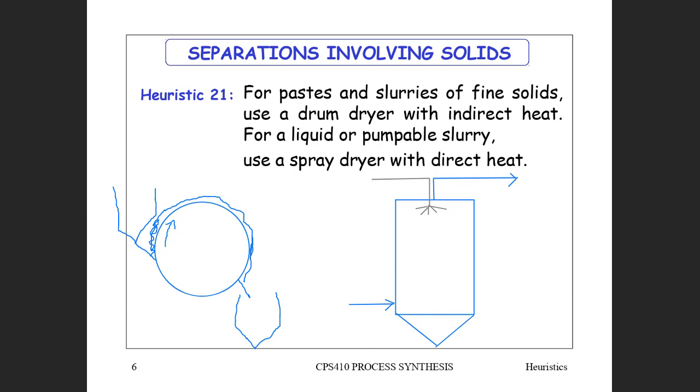So you make little droplets from the spray ball that are exactly the same size, and therefore as the droplets come out of the spray ball over here and they fall down, they are continuously drying, they're losing their water, counter current to this hot air that's coming in and rising up through the spray dryer. So if these droplets are all the same size, then you will tend to get the same size of particle at the bottom here.